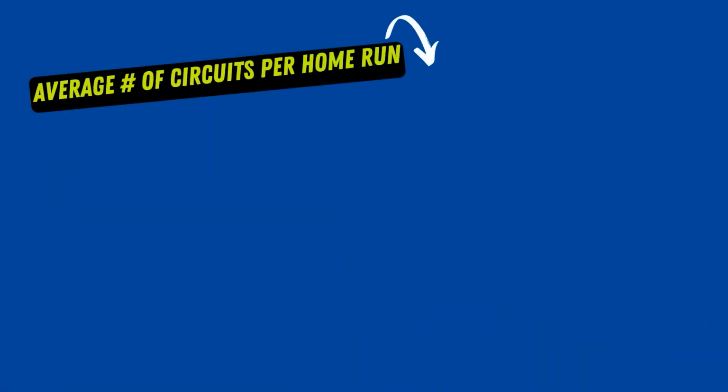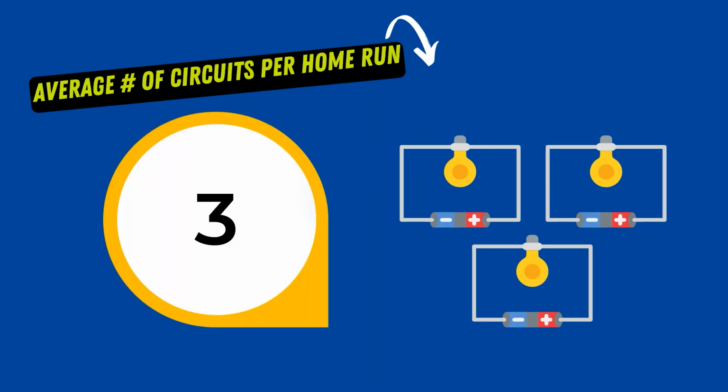Well, the formula that I came across, several years ago now, is based on the fact that what really determines the number of home runs is the number of circuits you have for the branch circuiting, which you can get from the panel schedule typically. Now for commercial work, three-phase, you can figure that a good average is going to be 3 circuits per home run.